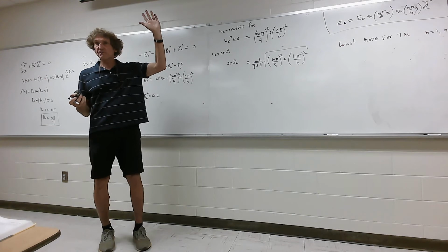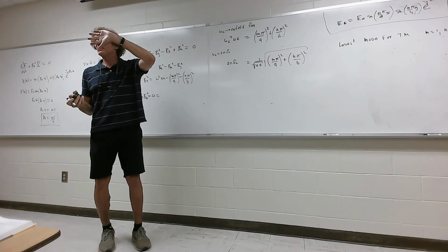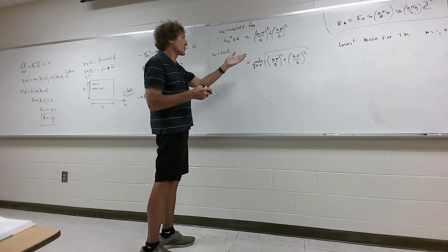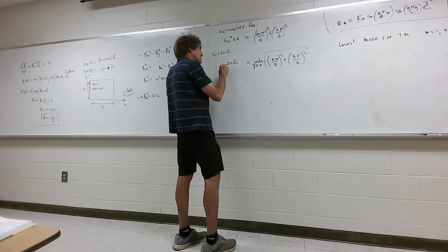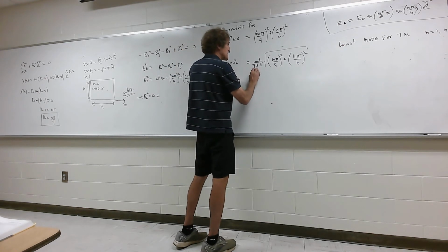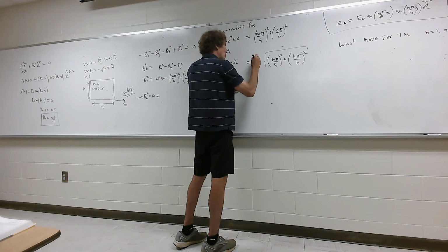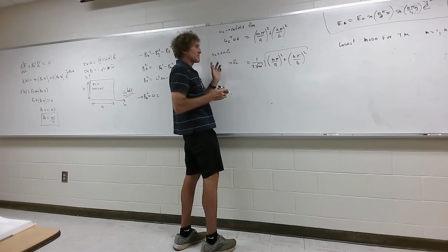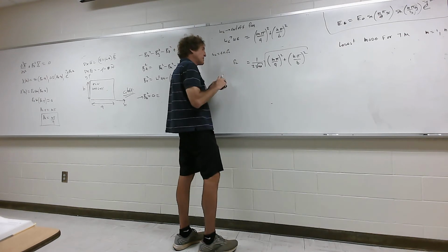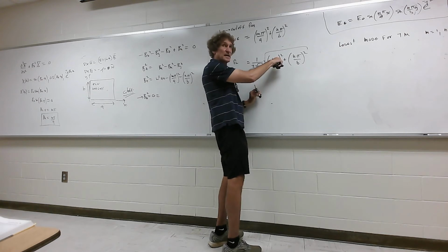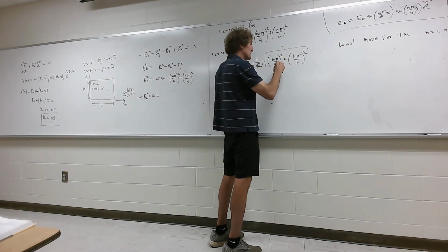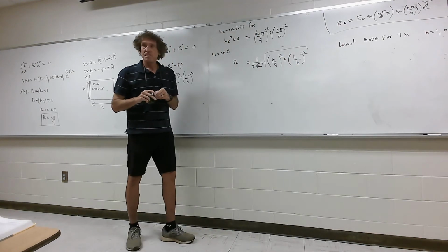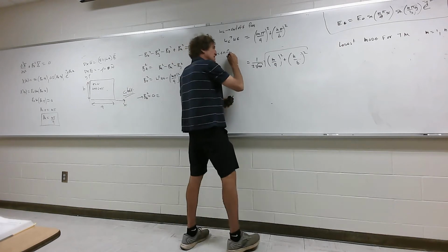I'm not trying to take too many steps forward before I explain it. Then I simply divide by 2, so that becomes 1 over 2 square root of mu epsilon here, and then I divide everything by pi. You'll notice if I divide by pi on that side, it's really dividing inside the square root by pi squared, so it gets rid of these pi's. And that is the cutoff frequency.